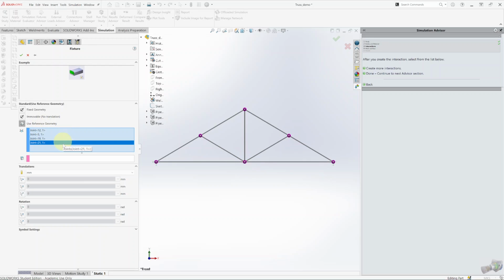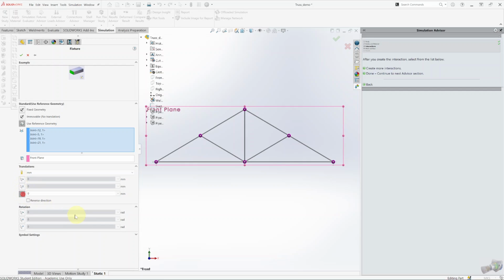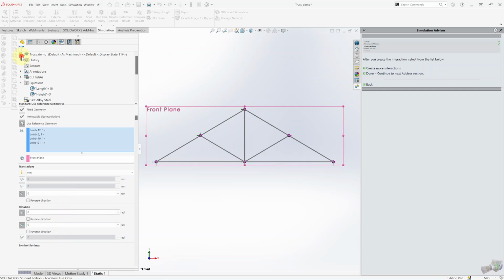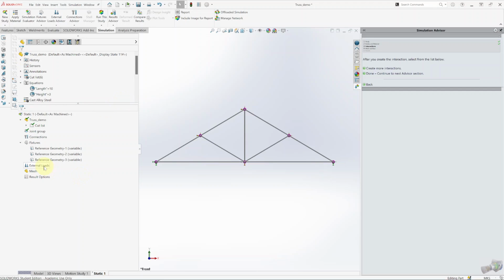Okay, this one. So you should have 4. Reference geometry is still your front plane, and that time we will want to leave free X and Y. The translation on X and Y, just block the Z and block the rotation on X and Y. So that should be gray, gray, white, white, white, gray. Enter. Okay. We will apply some external load.